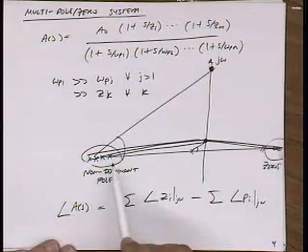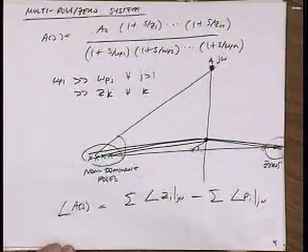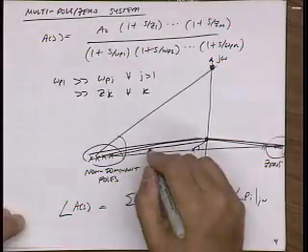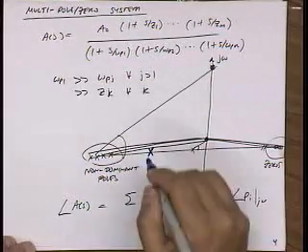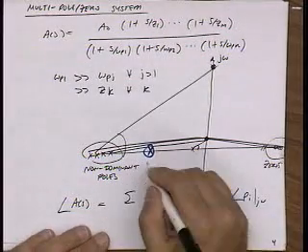So clearly, intuitively, it seems clear that I could, instead of dealing with all these poles and zeros, I could just say it looks like there's an effective pole here. So we call this the effective pole.